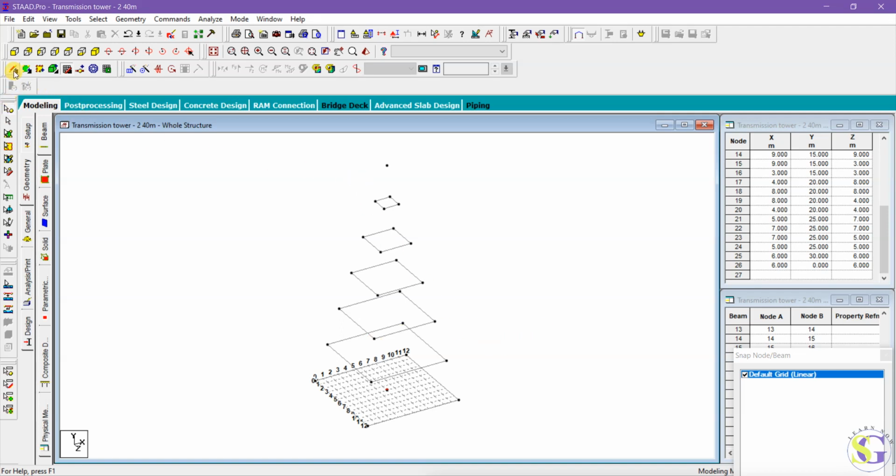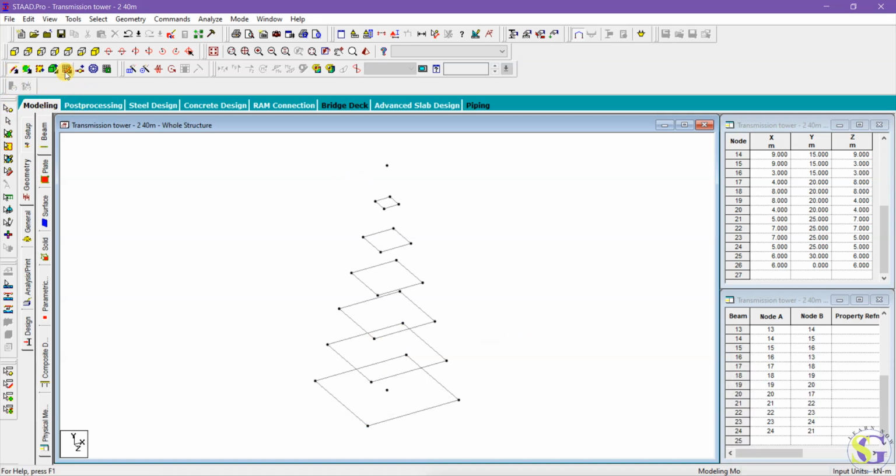Now what you do, add a beam. So we are going to add the beams for this. You can turn off the snap node. So just turn off the snap node, use the beam cursor, start from one side direction, just click one direction, and keep drawing the beams. Okay, so just keep drawing the beams. Next, over here, okay, so this way we complete one side.